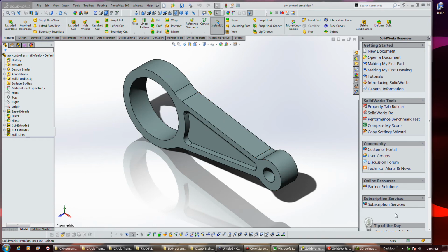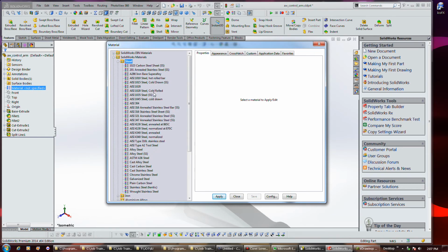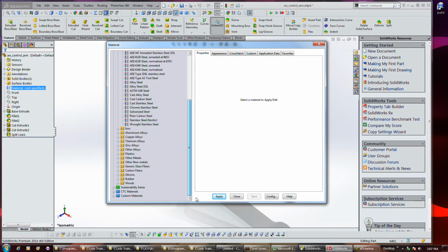For this I changed to MKS because this is going to be an MKS simulation. We're going to create a custom material apparently. And by the way, I just set it down here. So anyway, edit material, and we've already created these folders from CTC materials. That would be fine. Oh, still like materials. I guess I already did this. That's why it says CTC.